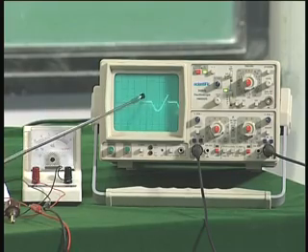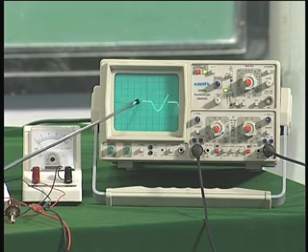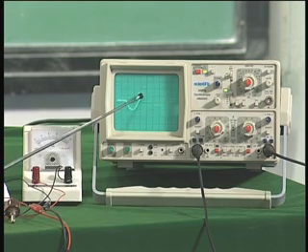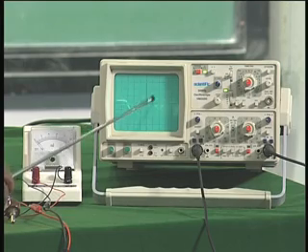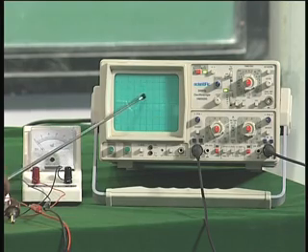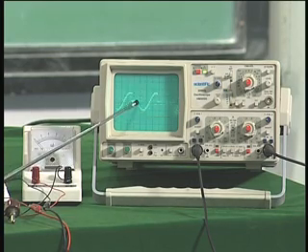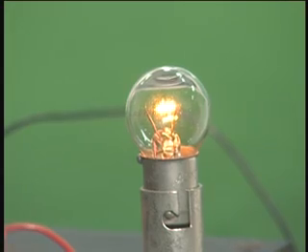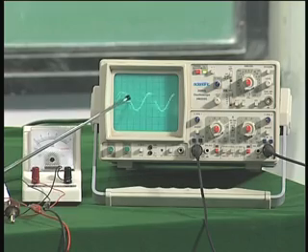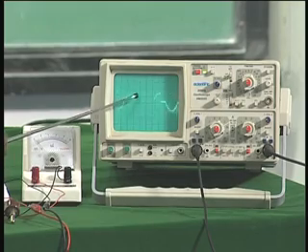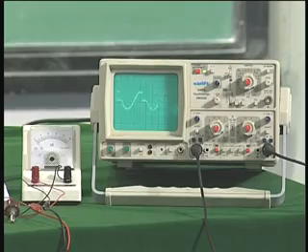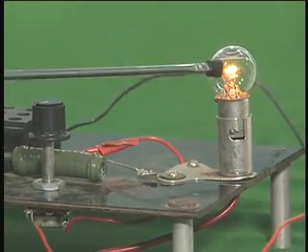So, you find it is triggering even at this point, when it will be around 5-6 volts, then the entire 18 volts, this peak entire voltage, is applied across the load. Therefore, the load is very bright. If I now increase that, you find this side it is very small, it is beyond 90 degrees, and therefore, the voltage applied across the load will be very small. If you look at the intensity of the lamp, now it is very small.